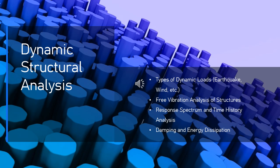Turbulence. Wind is often turbulent, with random fluctuations in speed and direction, which can cause dynamic effects on structures. Pressure distribution. The wind pressure is not uniform across the surface of a structure. The pressure distribution depends on the shape and height of the structure, as well as the wind speed. Types of wind loads. 1. Steady wind loads. These occur when wind blows at a constant velocity. For example, a structure subjected to a constant wind speed will experience a continuous force.